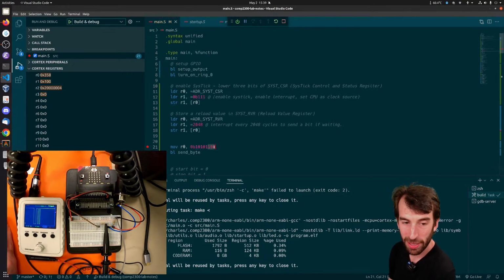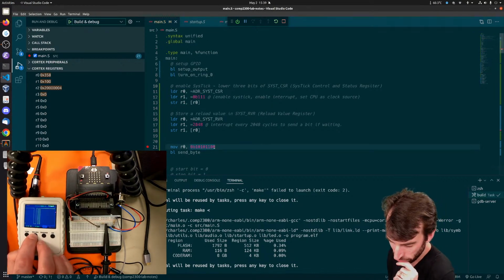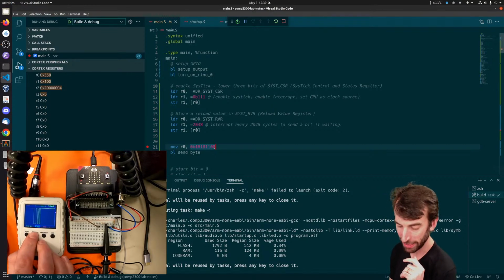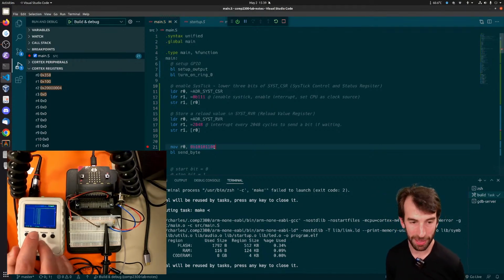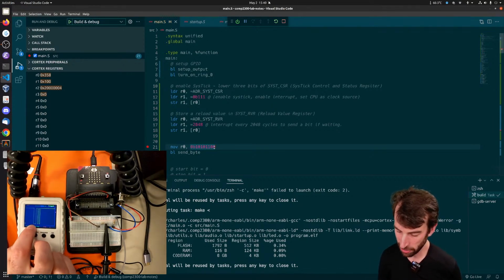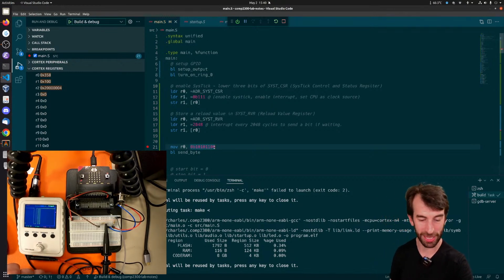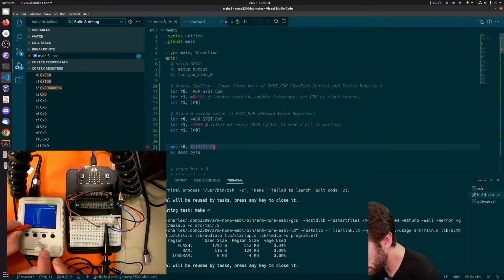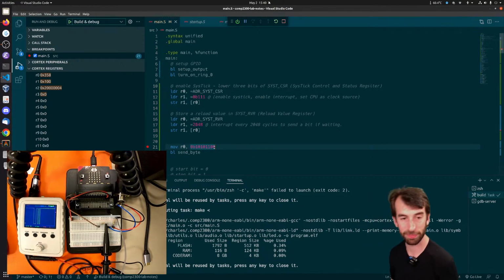And we can see, if we look really closely, the byte was 10101100, which should be two downs. I'll make it a bit bigger. Oh, I can't make it bigger because it's already happened. It's 2 down, 2 up, down, up, down, up, because we're reading it little endian. Start with a, I'll use this as a pointer. Start with a downwards transition, that's our start bit. Then we got our 2 0s, then we got 2 1s, 0, 1, 0, 1, and a stop bit.